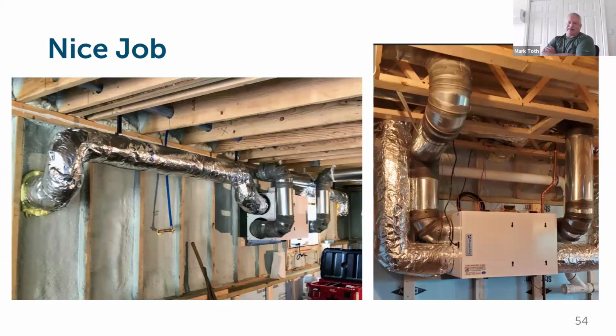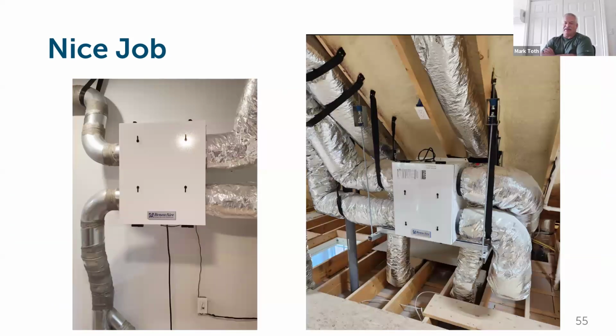And good duct systems, short, clean, insulated, sealed with foam, mastic sealant, that you couldn't have a better job. These are extremely well done systems. Very easy to tell the difference right off the bat. Some more nice systems here. In fact, this brings up something.